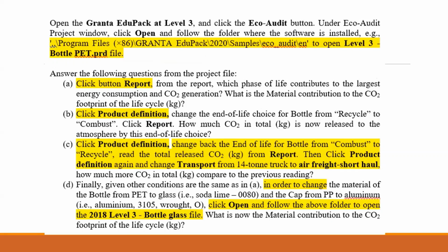We are going to open this file, which is in your C drive, program files, Granta EduPack, samples, Eco-Audit, EN. And this is under the level 3 PET bottles. After opening this file, we need to do a few things as mentioned here. Let's first open the file.